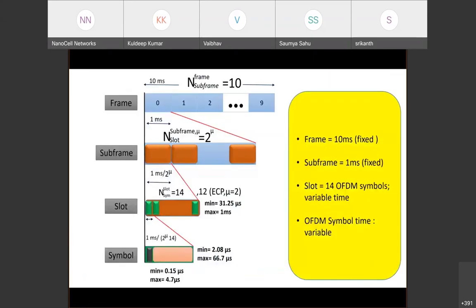Now, remember the OFDM subcarrier spacing is the finest button you could say in the whole physical layer, and you are giving flexibility with respect to that aspect. Okay. Now we want to build on top of it. Remember that once you make things flexible right at the bottom, you can start using that flexibility to have multiple other flexibility at higher layers. The next is the resource allocation related flexibility.